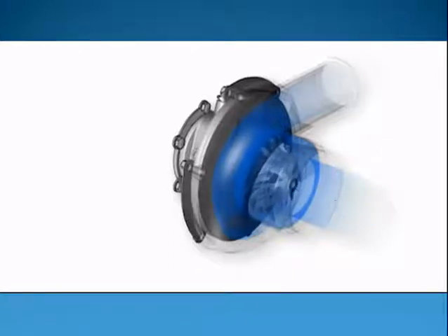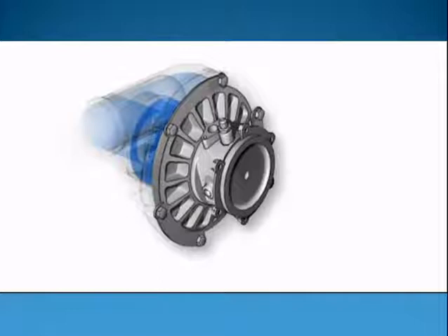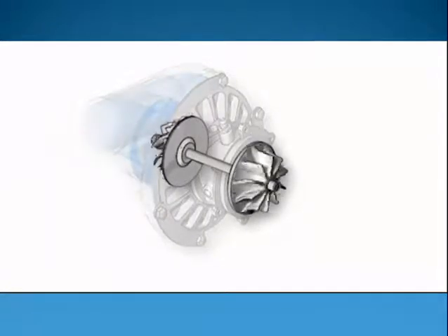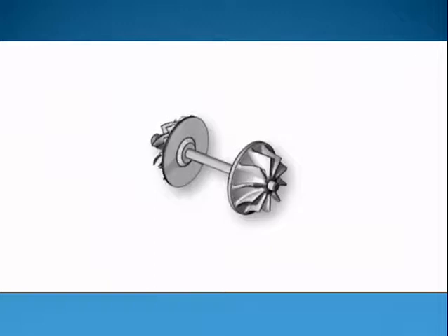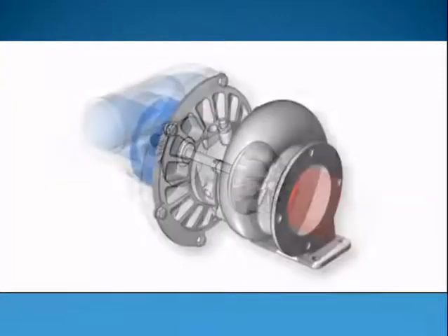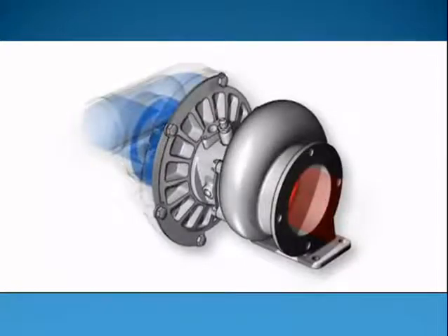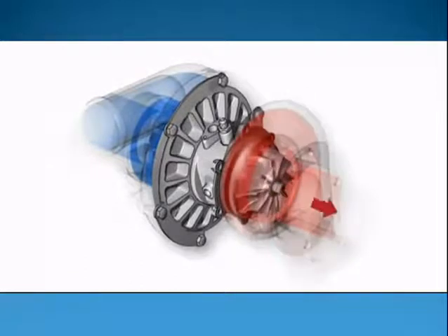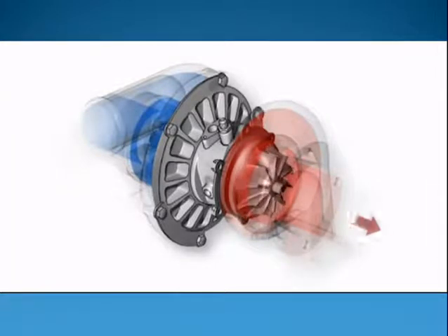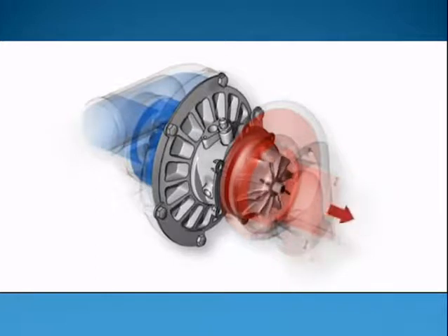The compressor impeller is located on a common shaft with an exhaust gas turbine. The exhaust gas turbine consists of a turbine rotor and the turbine casing. In this case, the pressure of the exhaust gases is converted to kinetic energy inside the turbine casing and supplied to the turbine rotor. The turbine rotor, driven in this way, converts the kinetic energy of the exhaust gas stream into energy of rotation of the shaft, thus driving the compressor.